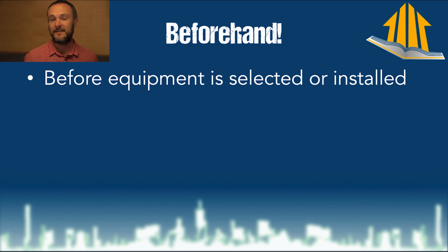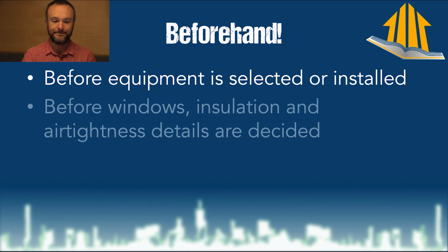I have been asked to do Manual J calculations that will result in a 2-ton air conditioner, because that's what we already installed. I do not do jobs like that. And generally, you can do that. And that's part of why I'm doing this video right now, is because there are lots of ways to game this software, accidentally or intentionally, to make it say whatever I want. And that's why it's important for you to know how this works, how to read somebody else's report, and how it can be cheated and gamed.